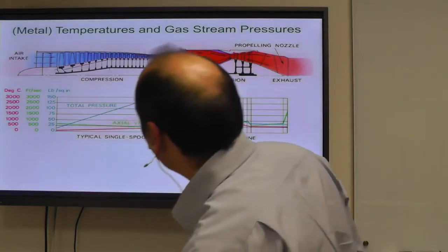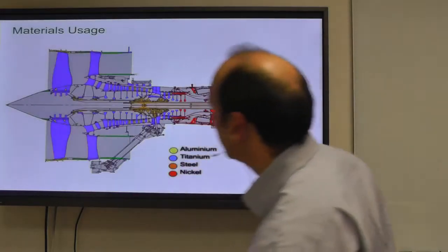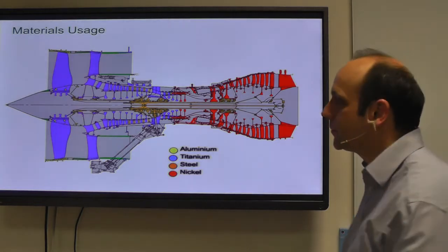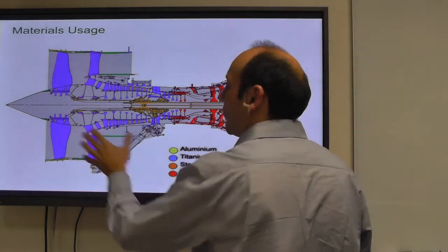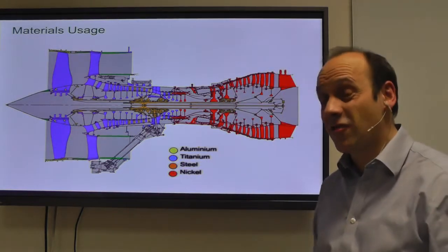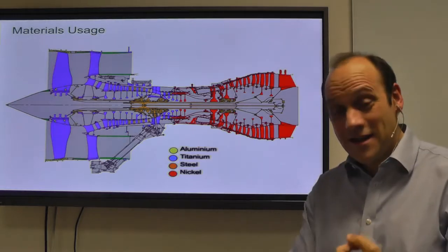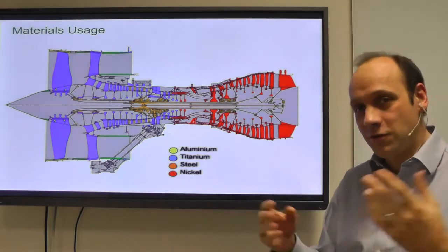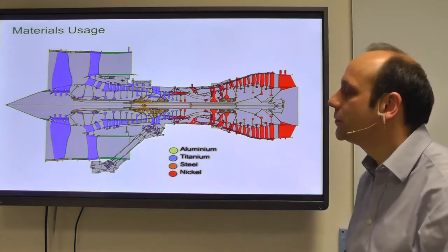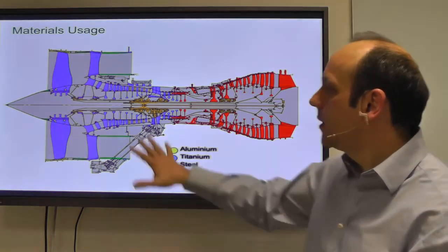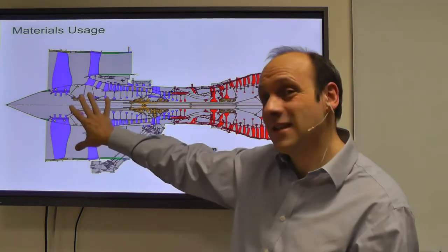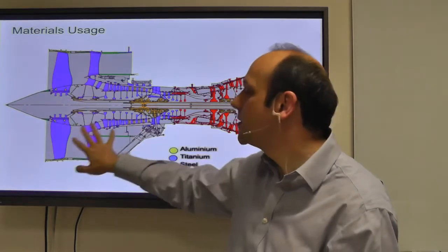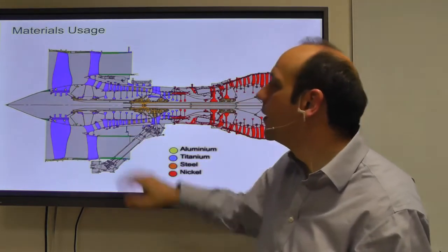That's how it works. So as you get hotter, of course, you run into the problem that the temperature capability of the alloy is limited. So you use titanium here for its good specific fatigue strength. That is its fatigue strength per unit weight. That is its strength under a fatigue load, which was much lower than its yield stress. So you use titanium, and its density is 4.5 rather than 8 for a steel. So that tends to take you towards using titanium at the front end.